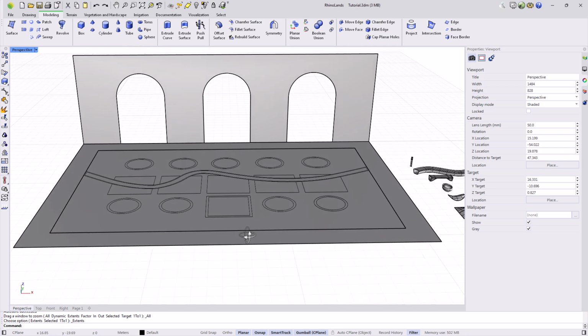To create predefined solids, such as boxes, pyramids, or cylinders, we have predefined shapes with which we only have to follow the steps in the command bar. First, we usually define the contour dimensions, and finally indicate the height.